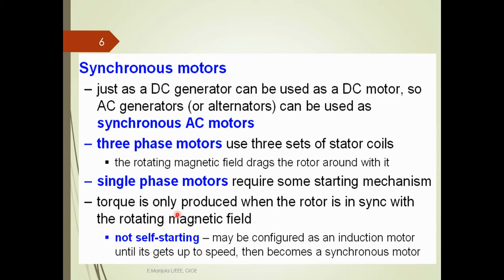It is not a self-starting motor; it may be configured as an induction motor until it gets up to speed, then it becomes a synchronous motor. We know that an induction motor will run by its own, whereas a synchronous motor is not self-starting, so we have to run it.